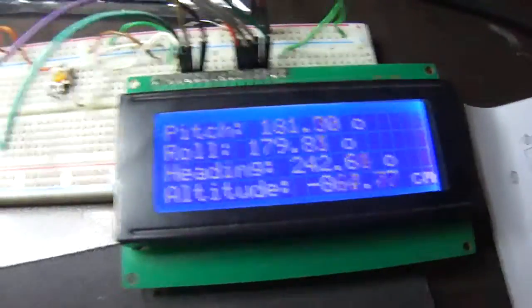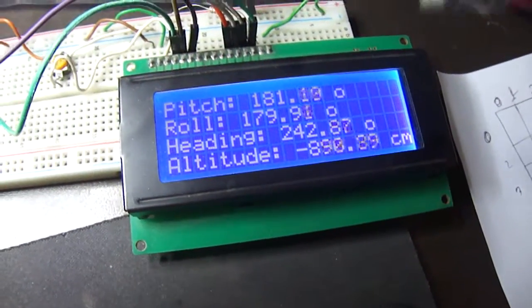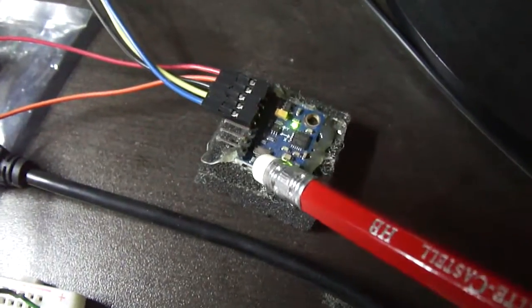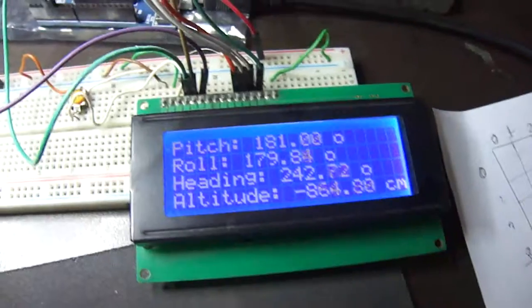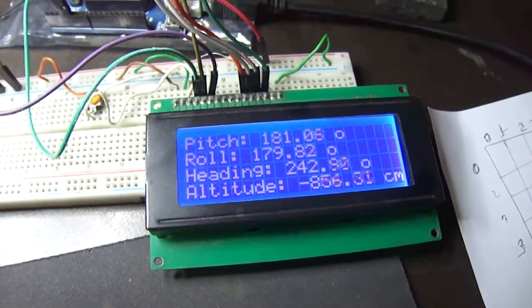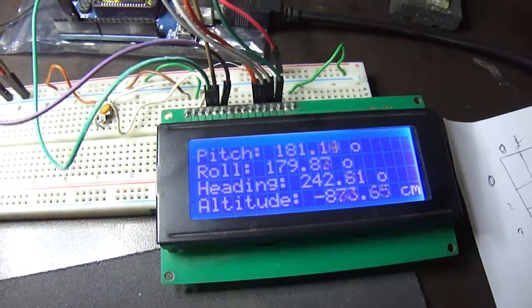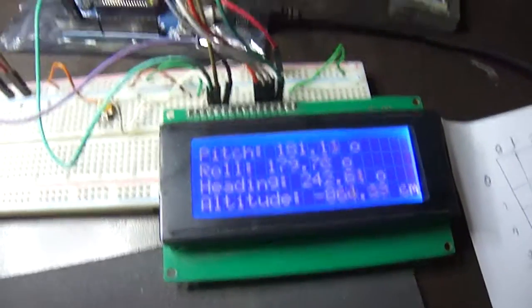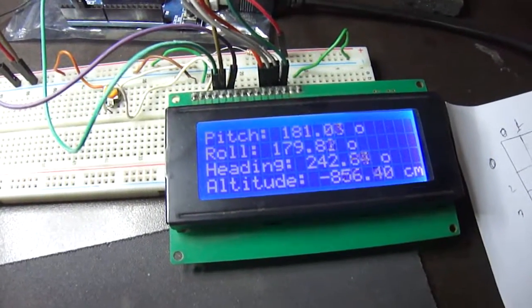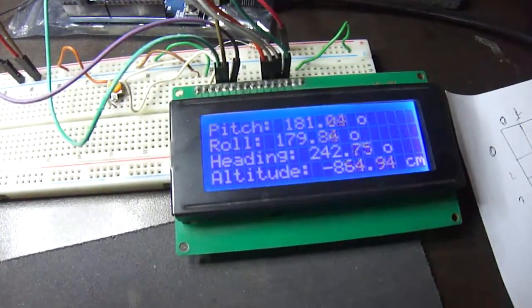And lastly, you see that the altitude reading is very fluctuating. The reason is that the barometer, the white sensor here, depends greatly on the pressure and temperature value, and in our code, we have inputted a standard pressure value, that is 1.013 times 10 to the power 5 Pascal. However, this is not right for where I am now. To find the real pressure value, you will need other instruments which are not available with the IMU board.